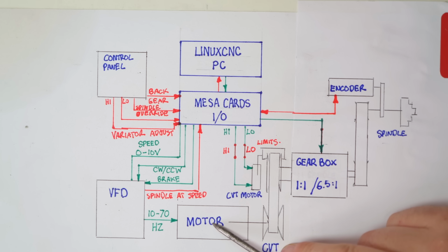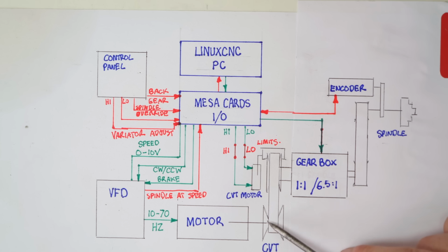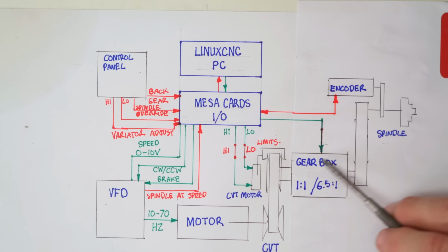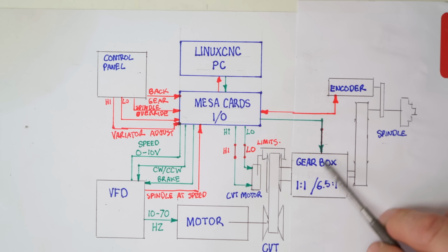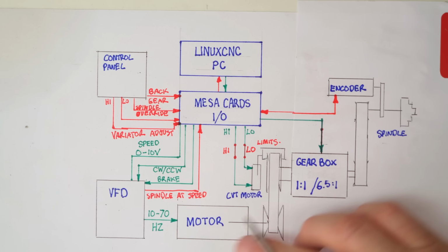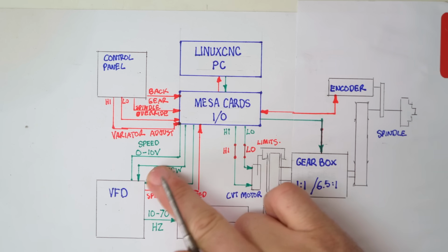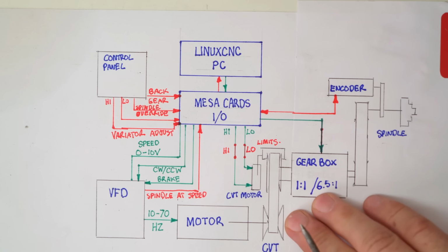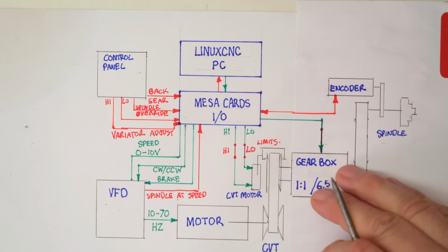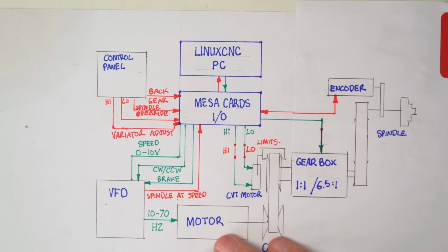It gets difficult because the change in inertia from lowest ratio here plus lowest ratio there versus highest ratio here and highest ratio there is a huge change in inertia. If you tried to do all the control with single proportional integral values, you'd end up either with oscillations at one side or with extremely slow performance at the other. And I don't really want either.